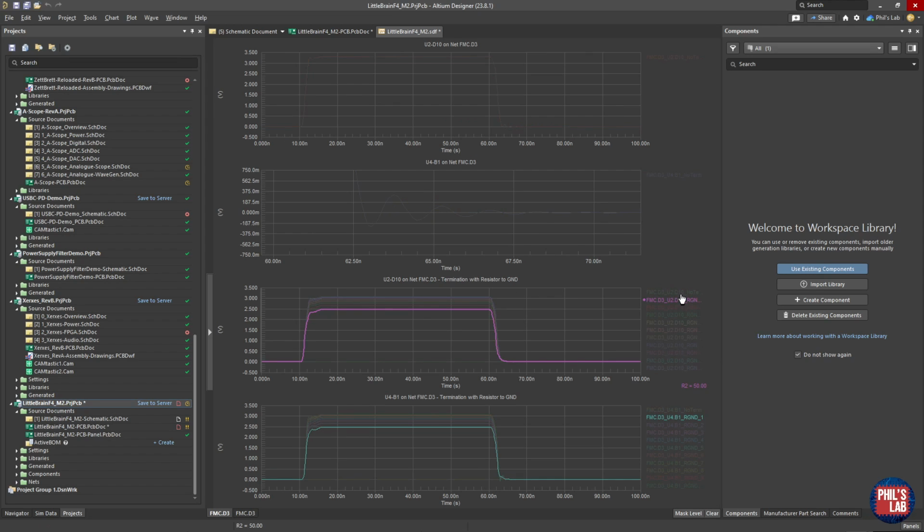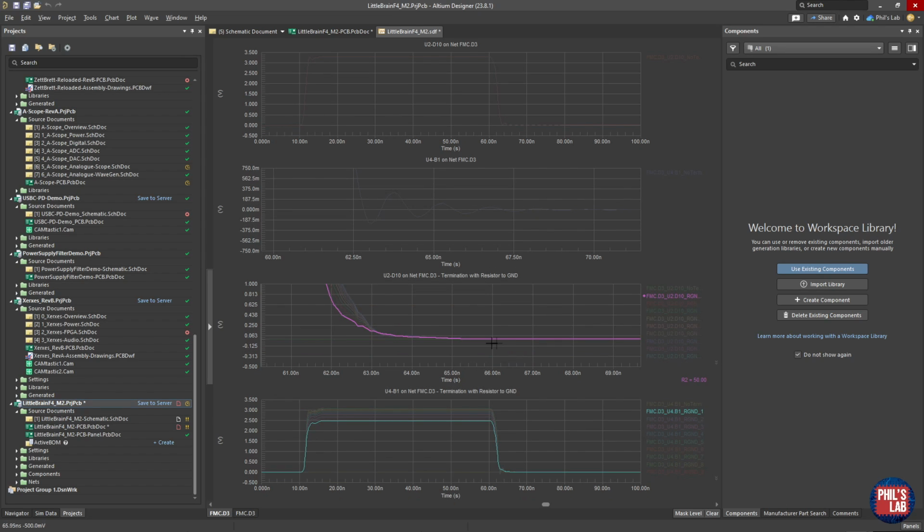And with our termination resistor of 50 ohms, looking at that same falling edge, we can see this is very smooth and we have significantly less overshoot, undershoot, and pretty much eliminated all the ringing. And this is why we use parallel termination, or termination in general.